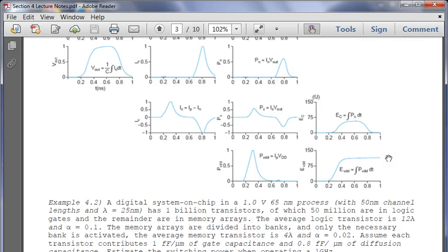You see how it's 0 and here it's not quite 0? This energy loss relates directly to this waveform here. We're talking about a degraded signal. If we're losing no energy, we get perfect hole and electron flow through the channel, then it would just be a perfect step response. If you have lower frequency, you're going to get a better step response. If you start having higher frequency, you're going to start getting issues such as electron collision, degradation of mobility, and so forth. So this is where all of these concepts kind of tie together.